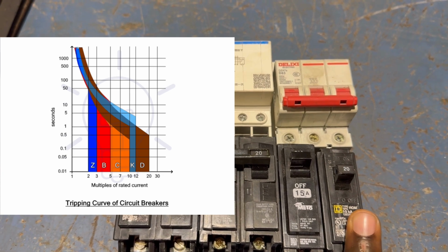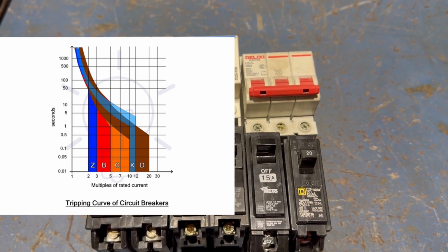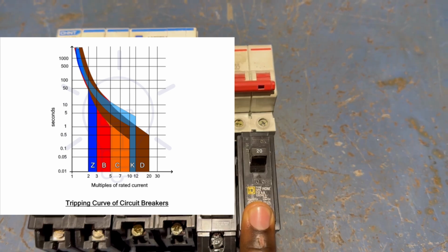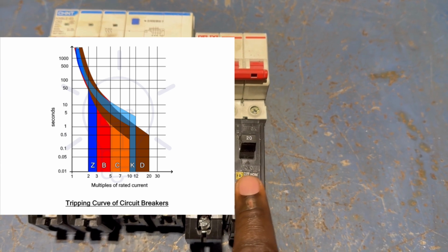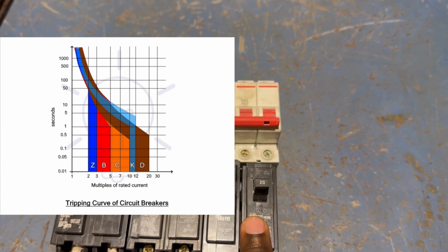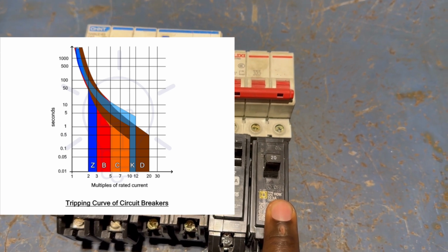So 3 times 20 is 60, and 5 times 20 is 100. So in order for this 20 amp breaker to trip instantaneously, it has to be 60 to 100 amp before it can trip.